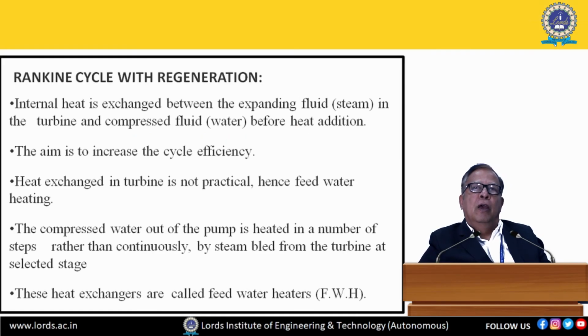Then finally, we will discuss the Rankine cycle with regeneration. So now here, internal heat is exchanged between the expanding fluid in the turbine and the compressed fluid before heat addition, right? So the aim of this cycle is to increase the cycle efficiency.